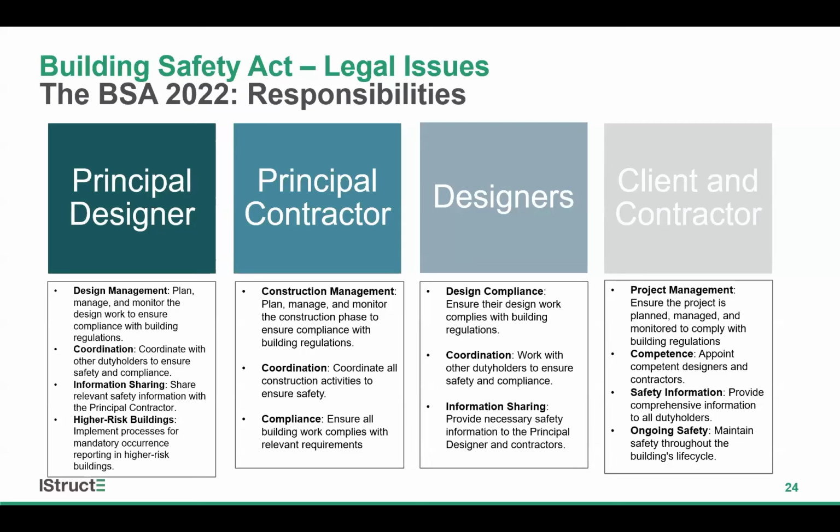I'll touch only briefly on the responsibilities for the principal contractor, but again, whilst the title is the same as the CDM regs, it's not the same role. So the principal contractor in the context of the Building Safety Act is a role during the construction phase and beyond. And the responsibilities as recorded on the slide include planning, managing and coordinating. It requires cooperation and communication with the principal designer and the client and other contractors, and the duty to assess the building work to make sure it complies with building regulations.